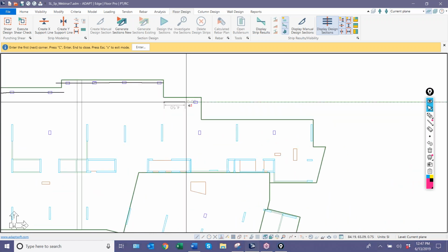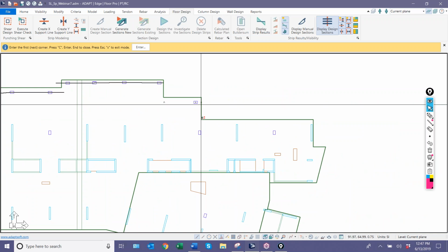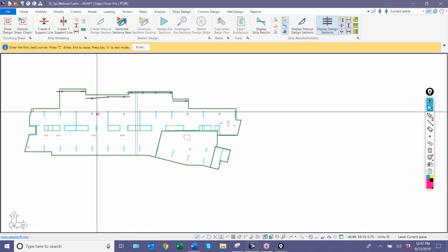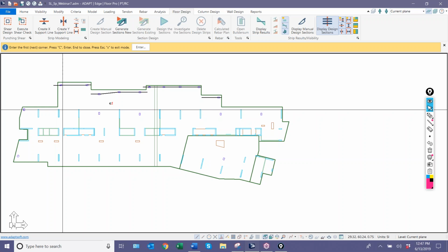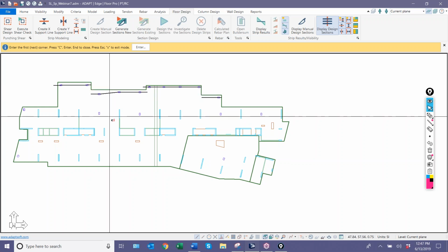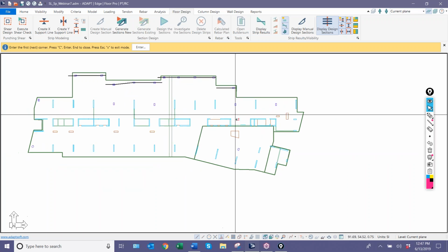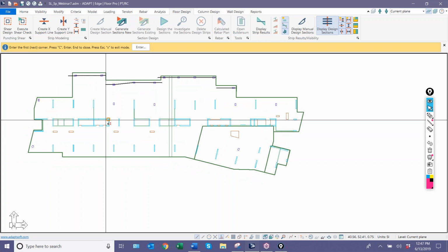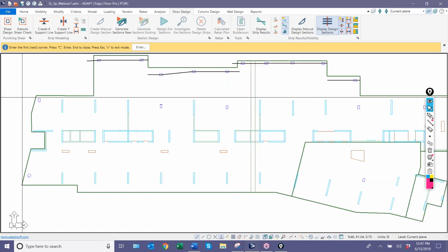I'm processing this one. I'm trying to keep everything in such a way that when I create a design cut, all of my distributed tendons intersect the design cuts at close to a 90-degree angle. For banded tendons, it's different because banded tendons might swerve and sweep more so than uniform, and in that case, we would kind of follow the same path as the bands.